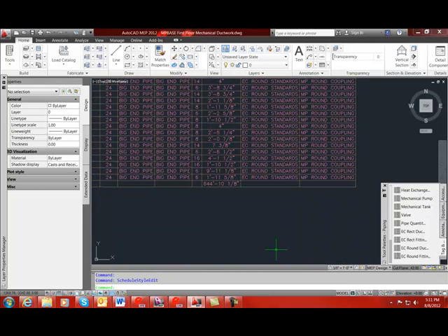Now please note that after the import you may get a message that says errors occurred, see the error log for details. Although the Fabrication for AutoCAD MEP error log can be used to jump from issue to issue to see what those errors might be, we feel that using the MEPFabCheck method described above will allow you to correct those items more efficiently. That concludes this video for assigning systems, fixing MEPFabCheck errors, and generating duct schedules.